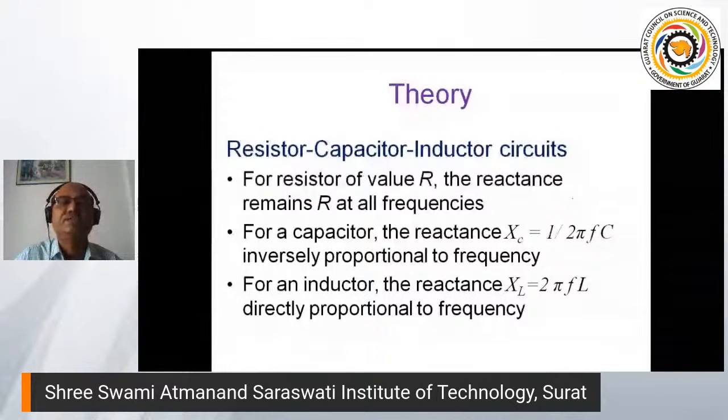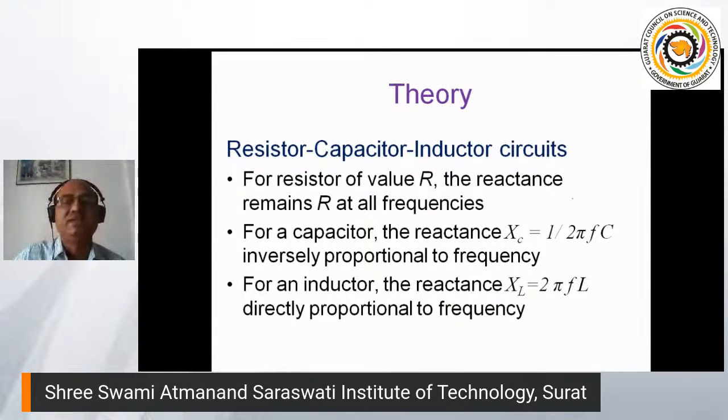We know that capacitive reactance is inversely proportional to frequency. If we increase the frequency, capacitive reactance will decrease. And in the case of inductive reactance, that is proportional to the frequency. If we increase the frequency, inductive reactance will increase. So you can say one is constant, one is inversely proportional, and one is proportional. Because of these three different responses of these three passive elements, it is possible to have it.